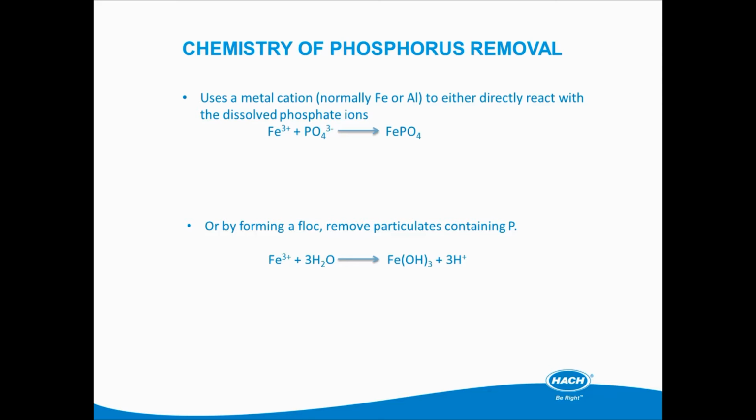When aluminium or iron acidic salts are added to water, the metal ion reacts with the water to form a fine floc of hydrated metal hydroxide. In the process of forming these flocs, the surface charge of colloidal particles is disrupted, and the colloidal particles begin to agglomerate. As the flocs form, these particles are attracted to and dragged out of suspension as the heavy floc sinks through the water column.